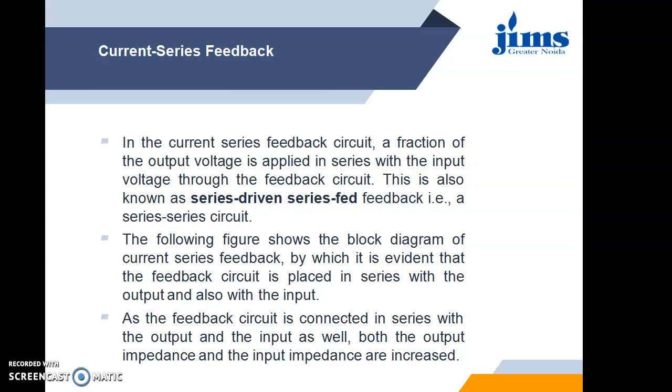In case of a current series feedback, the output energy applied is current, and since the current flows in series, the same value of the current gets in series, so the output port is in series, and input port is also in series as the name is suggesting, series feedback. So here at the input there is voltage applied in series and at the output there is current which is coming in the series. So it is the output current upon input voltage.